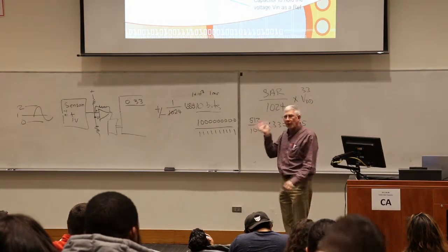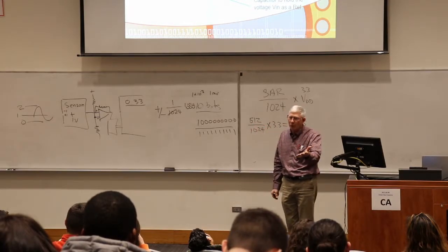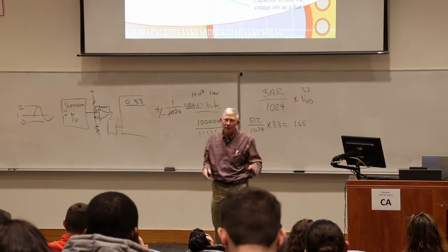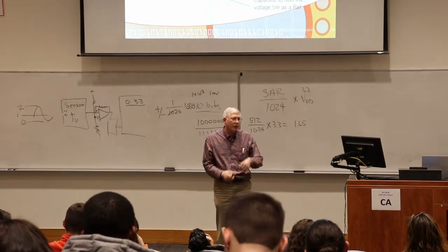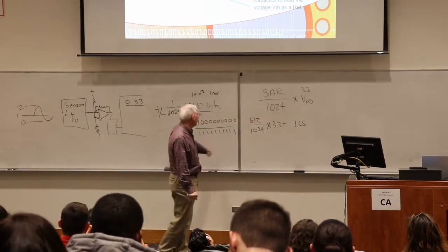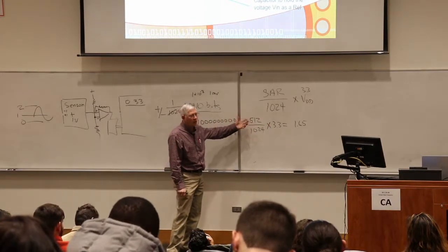So they use powers of 2 in these fixed voltage references for purposes of making your A to D values nice and clean. So if you want to clean up your A to D values, that's one way to do it, but you don't have to. It's not a big deal. You can do the math and see, and it's fine.